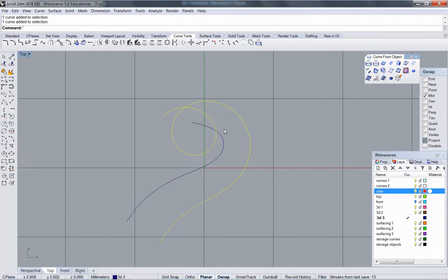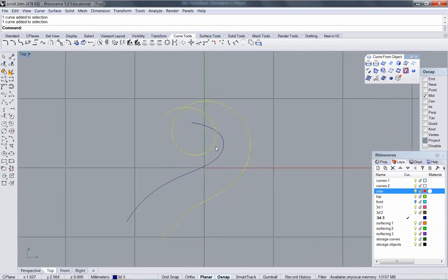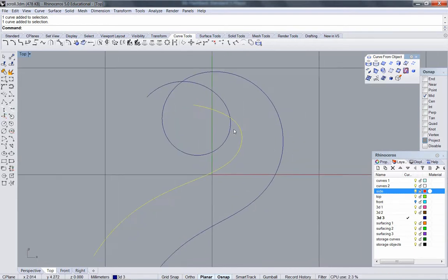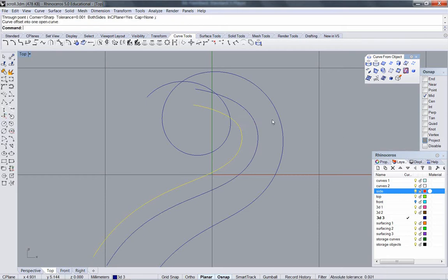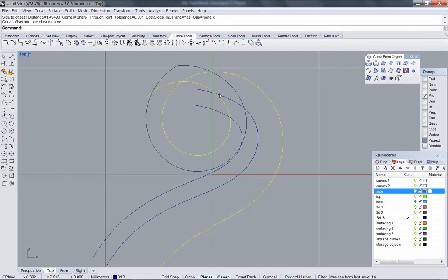Now I'm going to create this using fillets. I'm going to extrude a block of material and then use fillets to actually create my scroll. I'm going to use offset curves to strategize, to plan those fillets. What's important is that I get as much of a roundness to the sides of this as I can, but at the same time that I leave a central valley of material.